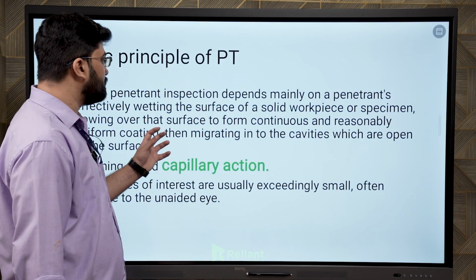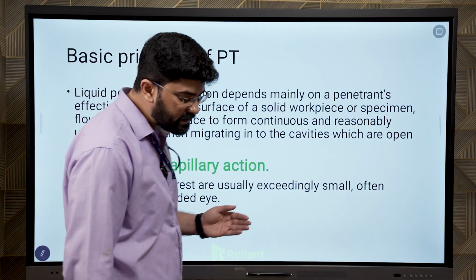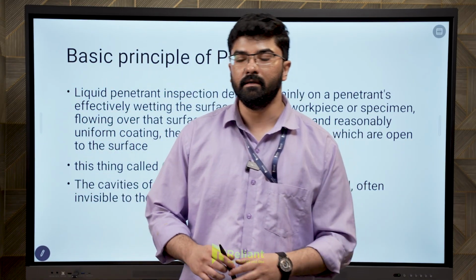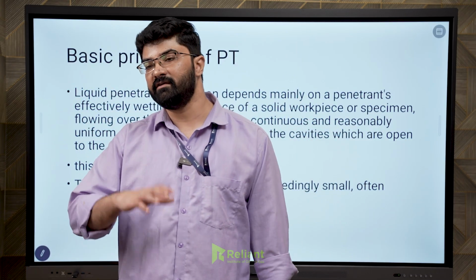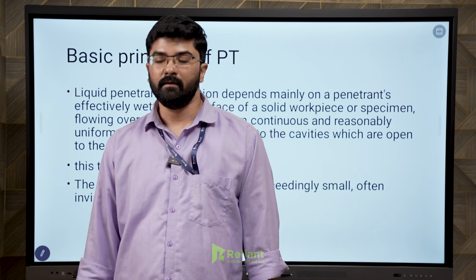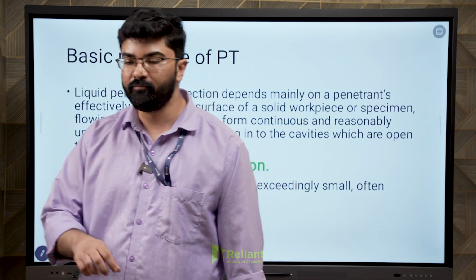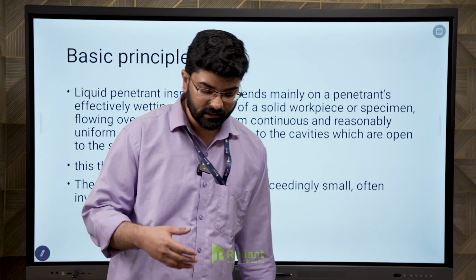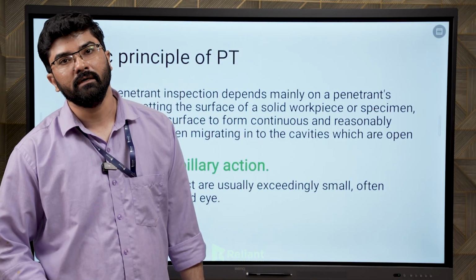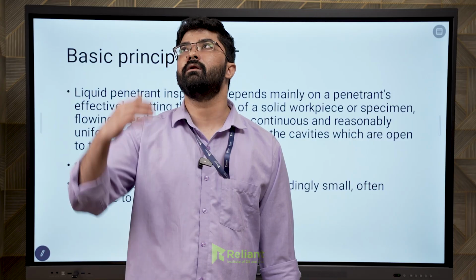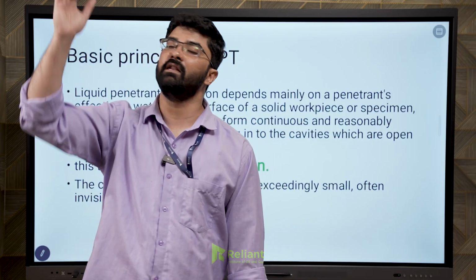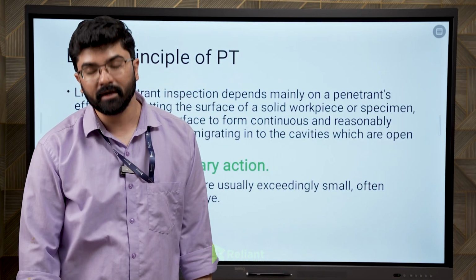So that's called the capillary action. That is why the capillary action does not depend on gravity. So even with different welding positions, we have the 1G position, fillet position, 1G groove position, butt weld position like 1G, 2G, 3G, 4G, even 6G, or the overhead position, overhead fillet position in a shipyard.